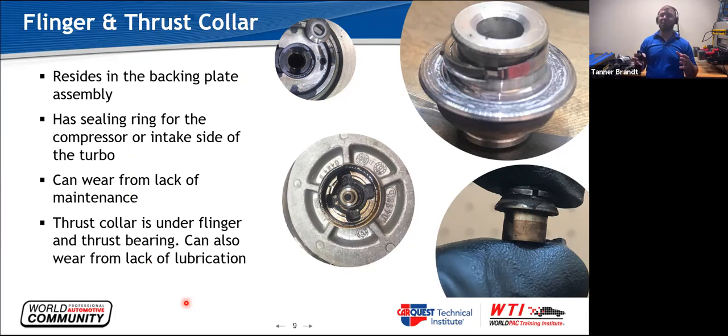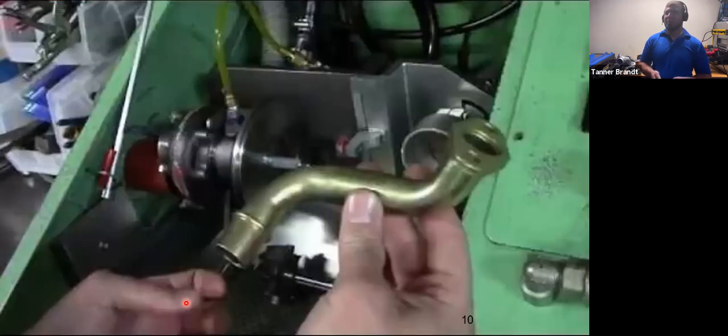So it's very important to understand that there is no rubber seal in any turbo out there. They all use this. Some of them may use 2 or 3 piston rings. Most are going to use 1 or 2. I would say the majority use 1. The only one you'll really see that uses 2 in automotive is the 6.7 Ford diesel. Everything else is pretty much going to use 1.